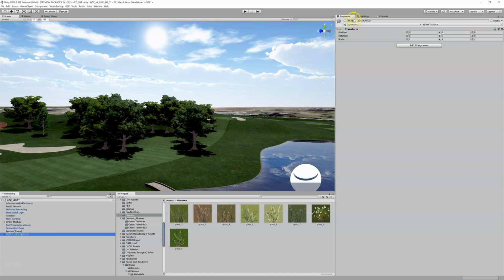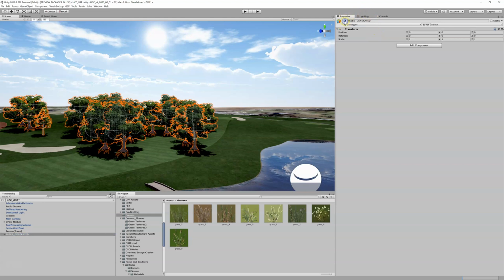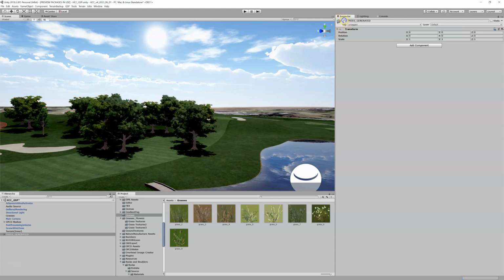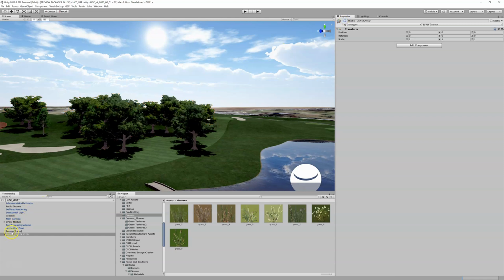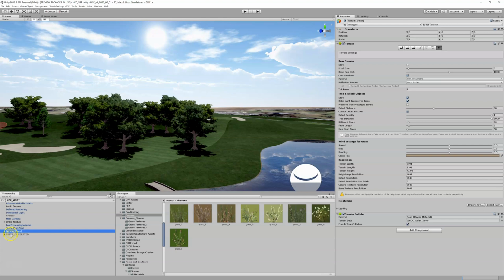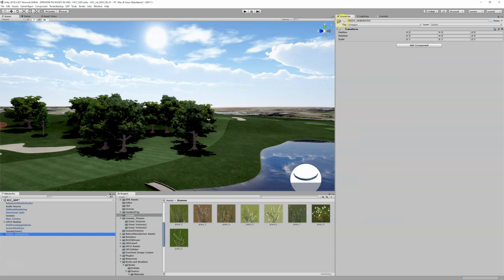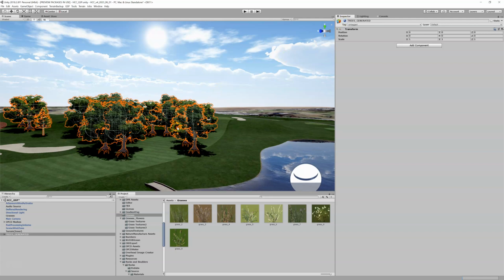Now this is disabled. I kept this disabled for now just to illustrate my point. I'm going to turn these on. And now what happens is you see, hey, there's all my trees generated. And if I turn them off, what happens? Well, they're still there. Well, they're not. What you're seeing when I turn these off are the trees on my inner terrain. So with trees generated turned on, I'm actually double rendering. I'm drawing these trees twice, which really impacts performance.